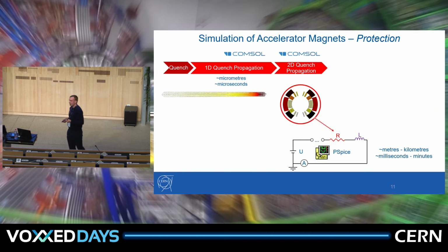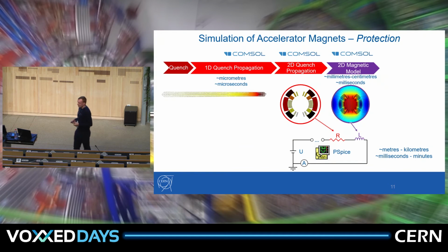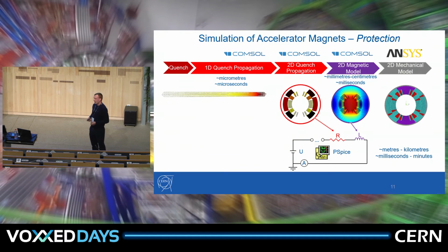So one thing is to study the thermal response. The other is to study magnetic field response during the discharge, because both of them are affecting the mechanical structure of a magnet. We have thermal contraction. As we heat something, it expands, but we have also Lorentz force. So current and magnetic field are creating a force that is acting on a coil. And this we need to study, especially in case of upgrades where we are going towards higher performances. So we need higher accuracy and high fidelity software.